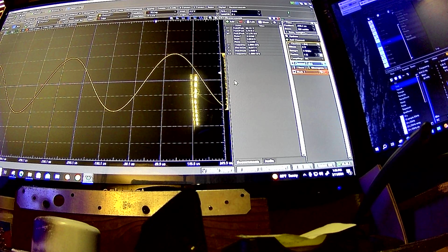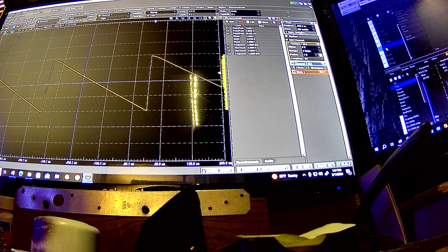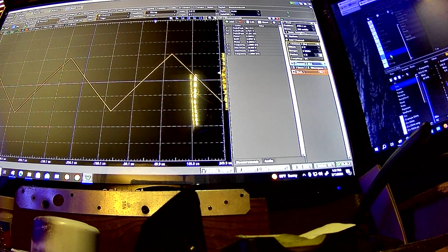But at any rate, like I said, that's giving you 200 samples, a total of 100 vertical samples. That's still less than what an 8-bit DAC would do. An 8-bit DAC would do 256 vertical samples. It just puts things in perspective: you can only do so much, even though you think, hey, 500 kilosamples, that's high speed. Really, we're sitting here at 2.5 kilohertz and only just starting to have things look really, really smooth.